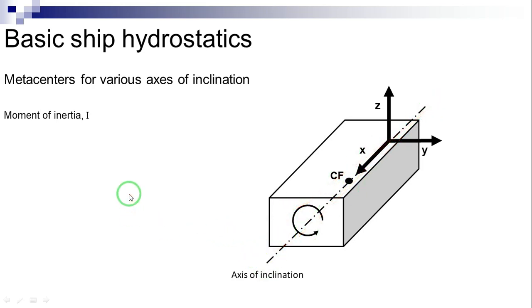It can be shown that there is a pair of orthogonal axes such that the moment of inertia about one of them is minimum and about the other maximum. Then the metacentric radius corresponding to the former axis is minimum and the one corresponding to the latter is maximum. Correspondingly, one of the metacentric radii is minimum and the other maximum.